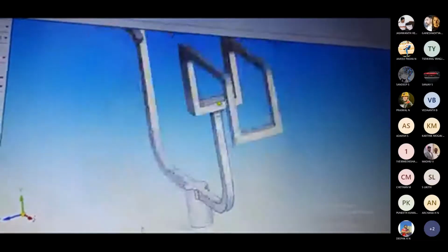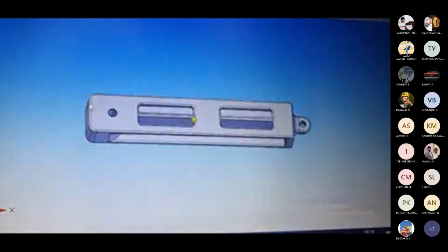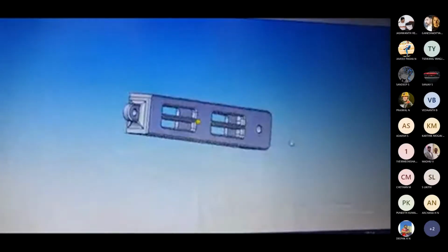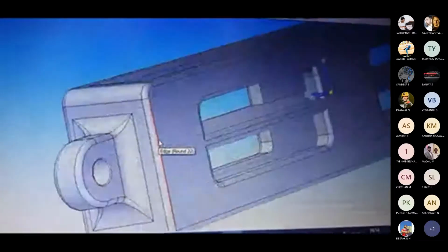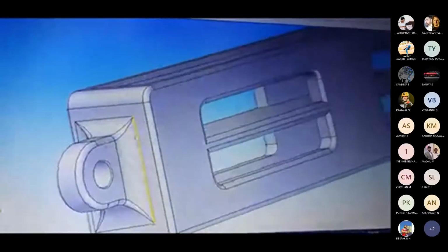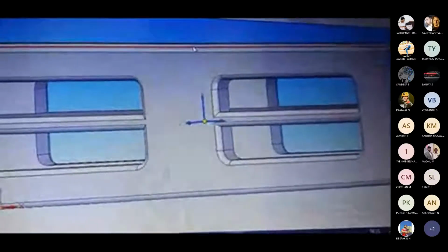This is directly a CAD model, and it cannot be given as an input. It has to be converted to STL format, and we have to fix the layering and the quality. Whether it has to be hollow inside or filled, or any fashion of filling, all this information we have to give, to see whether the quality we expected is coming or not.